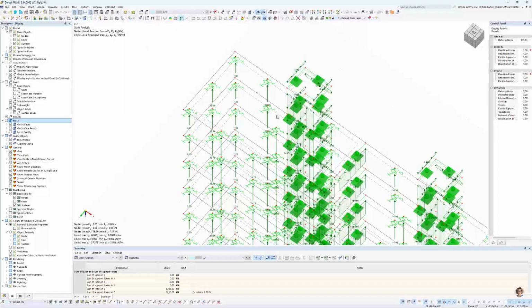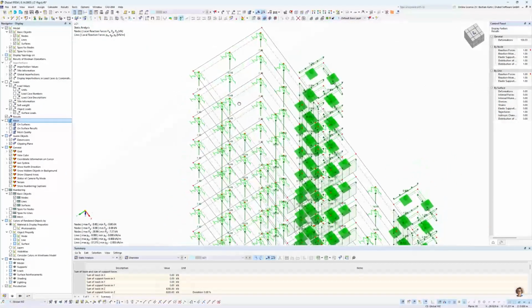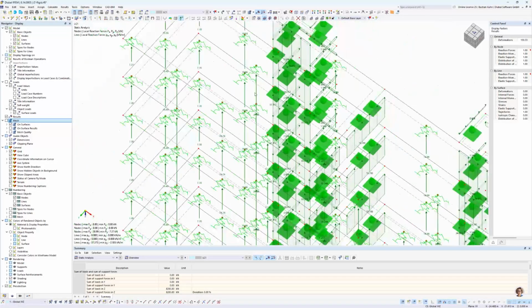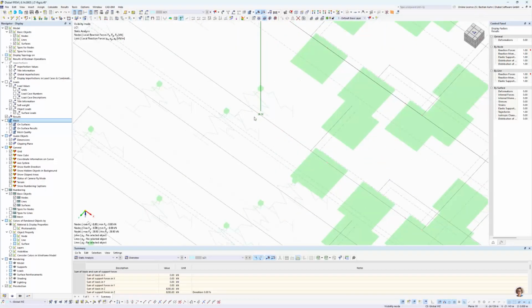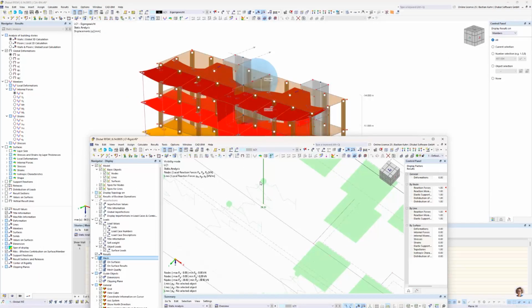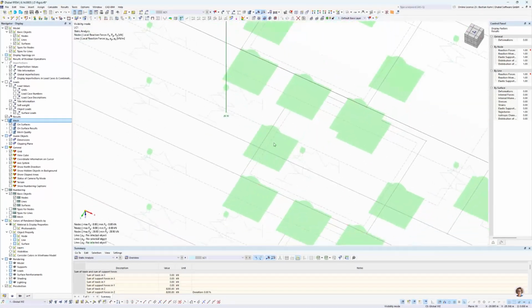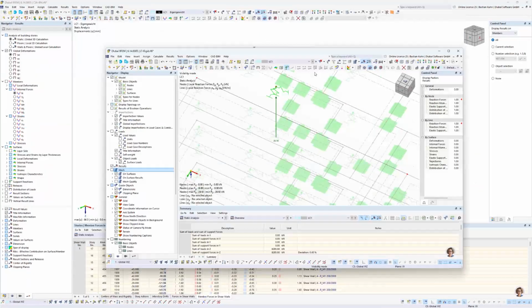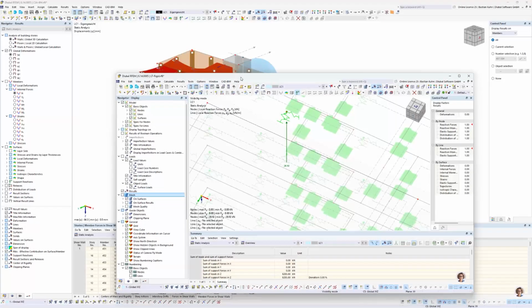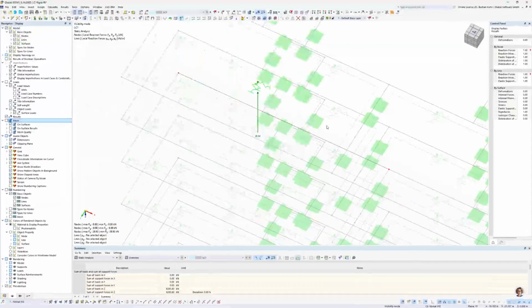And get out of this rendering for the center. So you see here, not so good to see, but maybe we do it similar to what we did before, just show this one. So it's 28.9, which is the same value that we had here for the center column. And that's the point where we're looking at. And of course, it's the same vertical force because that is the model that's in the back of this, when you define this load transfer type, semi-rigid or rigid in this case.